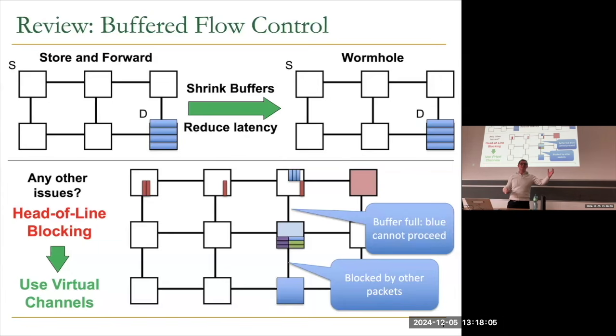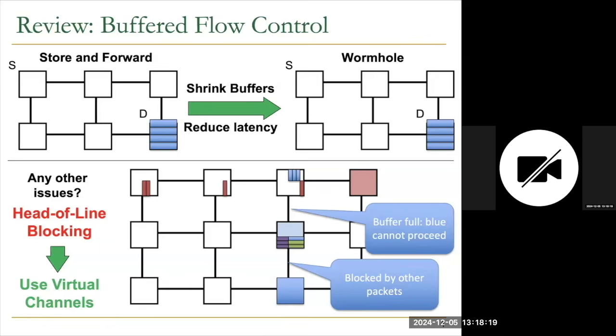You have in-order execution of instructions, which is terrible for latency tolerance. You have completely out-of-order execution of instructions, which is bad for complexity, but good for performance. Think of virtual channels as a way of achieving part of the out-of-order scheduling benefits without having complexity commensurate with out-of-order scheduling. In processor cores, we're actually very used to out-of-order scheduling of instructions, right? In networks, maybe we're less used to out-of-order scheduling of packets, but it's good to think about that going into the future. Okay, so that's virtual channels.